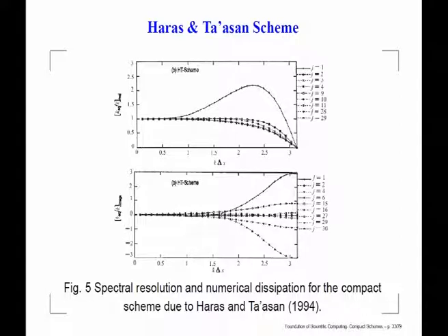The Hu-Hussaini scheme was an eye opener, in the sense that it opens up possibilities of developing schemes with very high resolution. Why do we say high resolution? In the Adams scheme, k equivalent by k, the real part was close to 1 up to 1.5, and after that it started falling off. But you notice here, for the interior stencils, the middle of the domain, if you leave out the boundary points, it remains flat all the way up to about 2.2, 2.3. Maximum you can go up to pi, and this scheme helps you go almost all the way up to the theoretical limit.